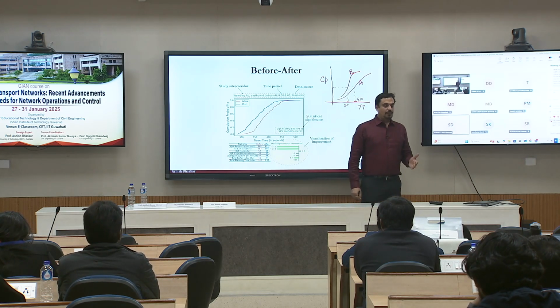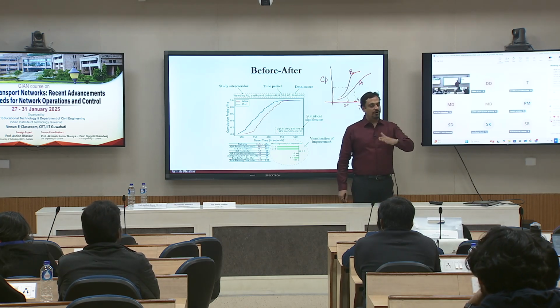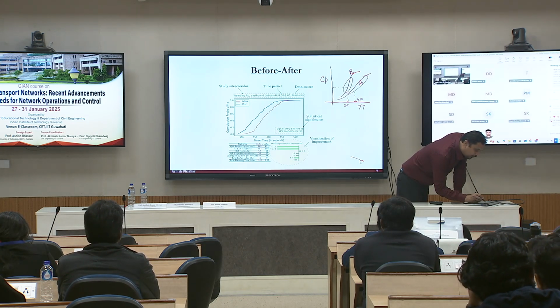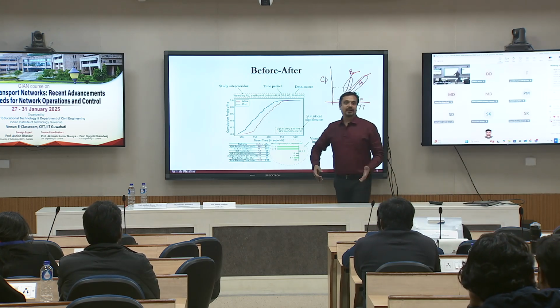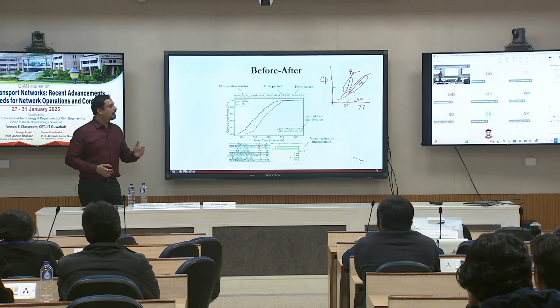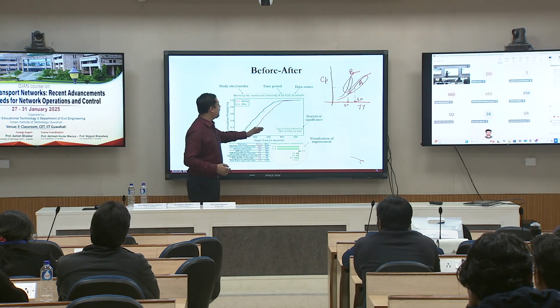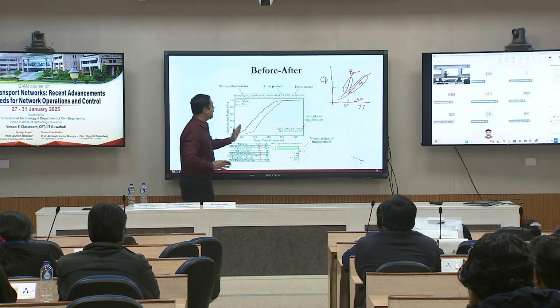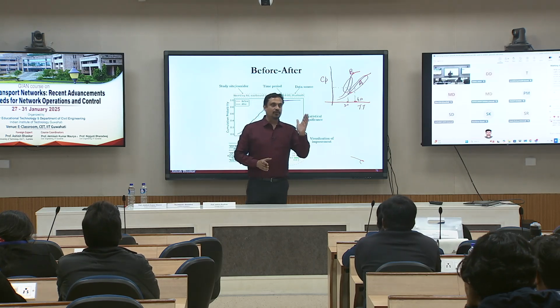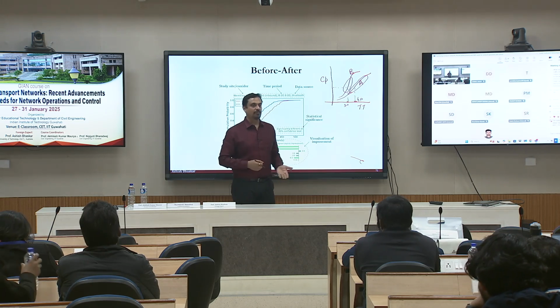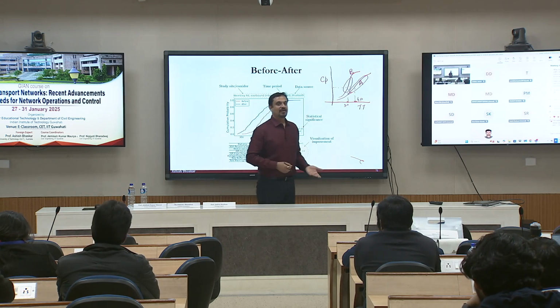Moreover, the slope has also gone down. Most of my data points were concentrated around 300. Now they are concentrated all the way from 300 to 500. So I have more spread and less reliability in the system. In this example, there was not much difference in terms of reliability because the slope looks quite parallel. But if my slope would have gone more steep, I would say I'm actually having a more reliable travel time compared to the previous case.